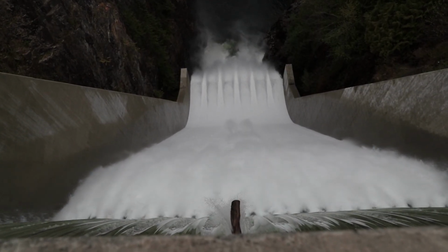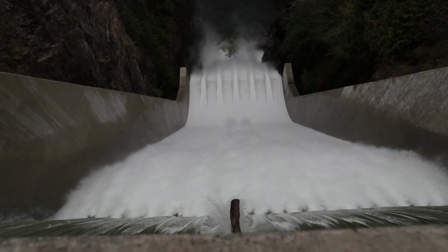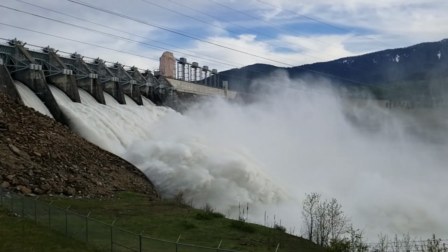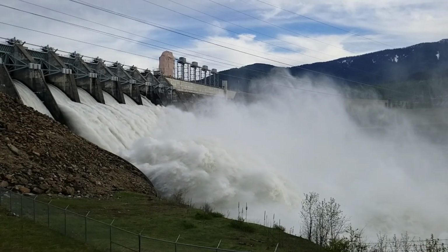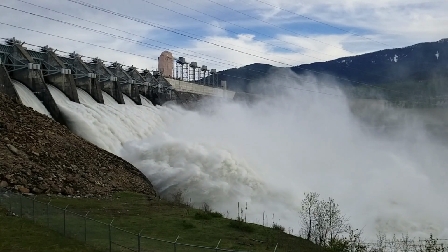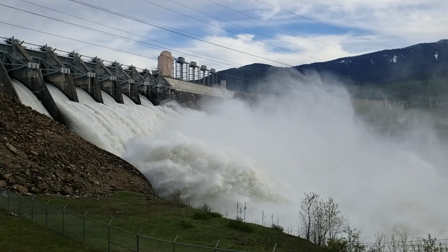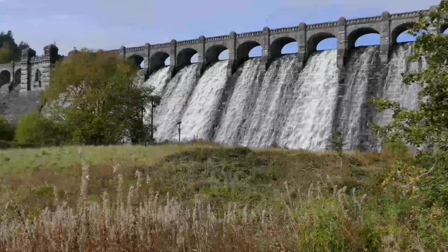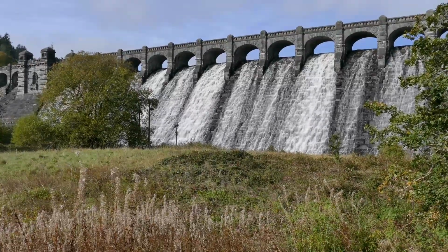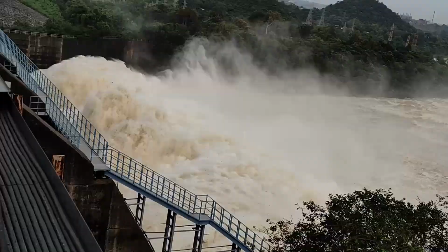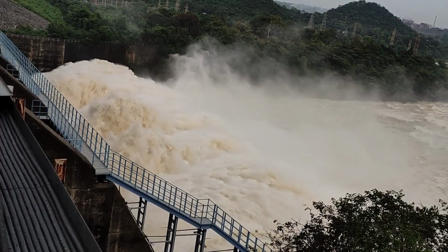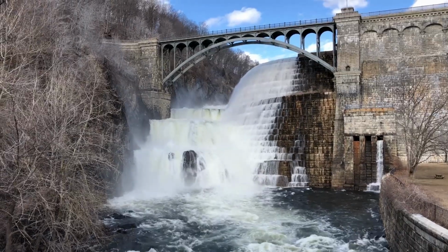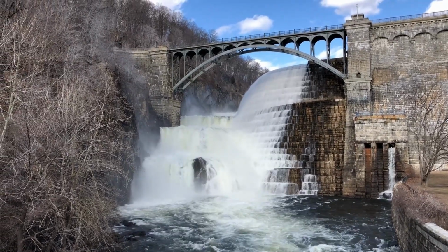The next step is to check for energy dissipation. Because water leaving the spillway moves extremely fast, if not controlled, it can erode the riverbed downstream. Engineers therefore design energy dissipation structures. The common ones include the stilling basin, flip buckets, and plunge pools. The major motive of this is to slow down the flow, transforming the energy from supercritical to subcritical flow, so that there is no scouring and erosion on the downstream side of the dam.